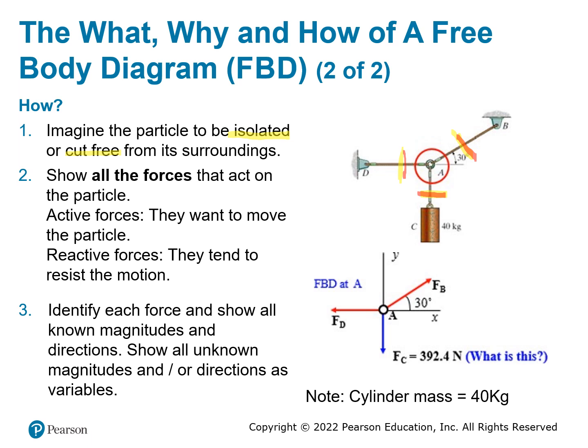And tension always points away from the object. So if your object is this one here, our tension force is always away from the object. So it will go outwards, away from this point. So this is going to be your tension force. Same thing for this one. You cut this one out, you're going to have a tension force here. This is going to be a tension force away from the point A.